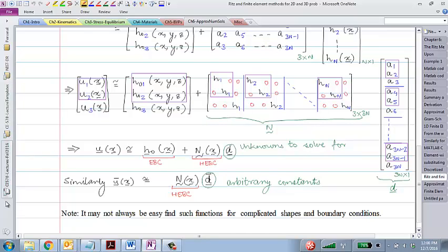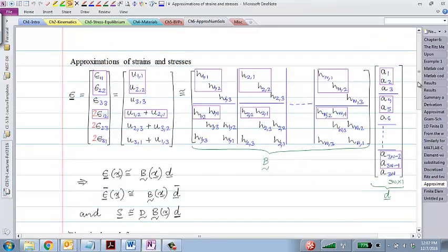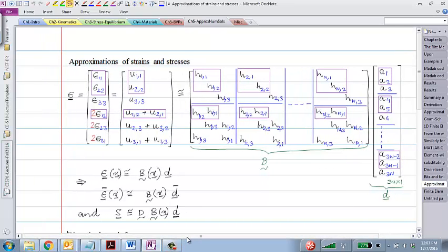In 1D, it's easy. I can easily pick a point. If the function goes to 0 there, then I'll create a polynomial with a root at that point. But in 2D, I have to make sure whatever function I pick satisfies the h1 condition, first of all, that it has to be smooth, its first derivative has to be square integrable, and the fact that it has to go to 0 wherever the real displacement is specified. That's not as easy in general, but there are nice ways to enforce that. And I'll talk about that in this page or the next page.